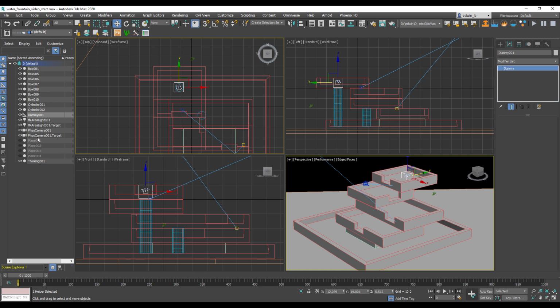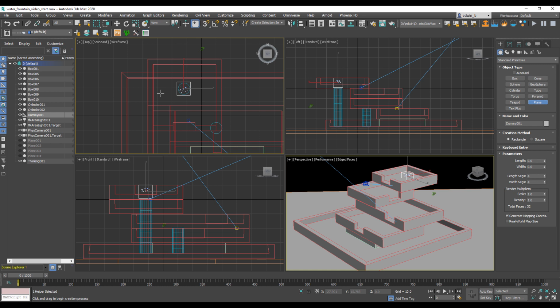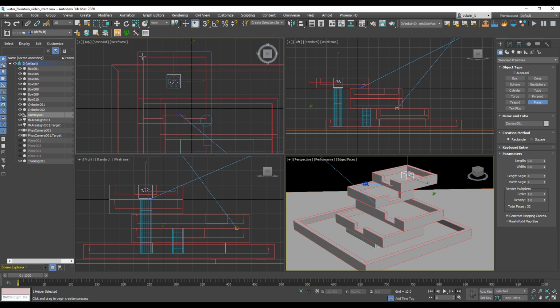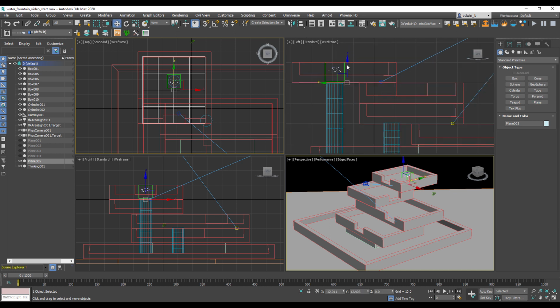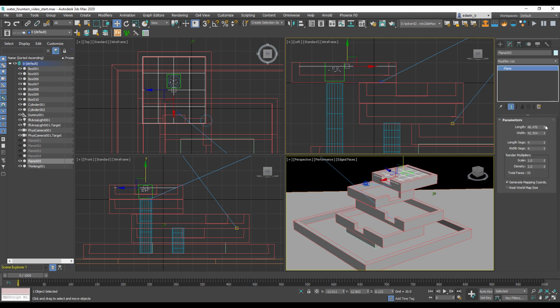To do so, I'm going to show you how this works. We already have some planes, but I will show you how in principle this system works. We create a simple plane, nothing fancy, nothing special. And the plane should just cover our container. So I'm just dragging around the plane, and we need to be kind of careful how big our plane is, because we don't want the plane to intersect with the border walls, because then we would create particles inside of an object.